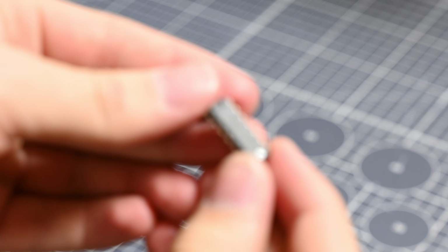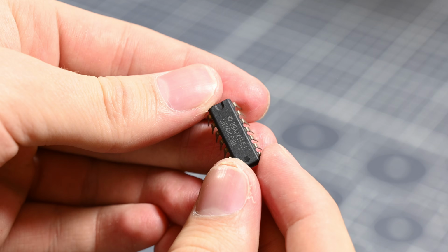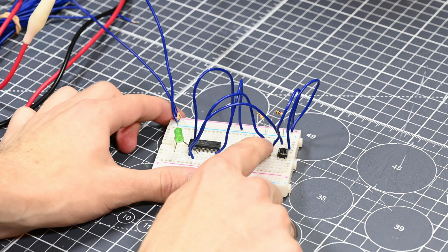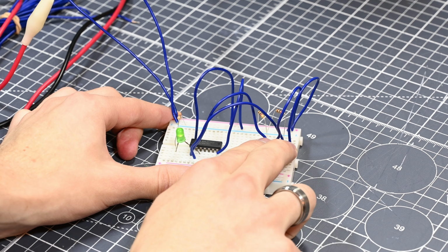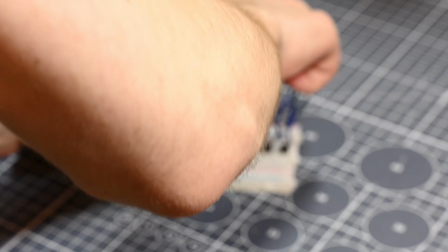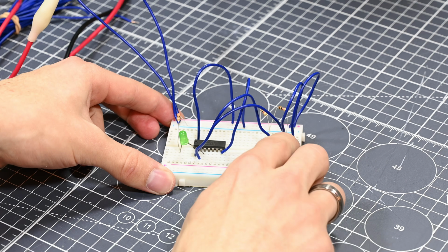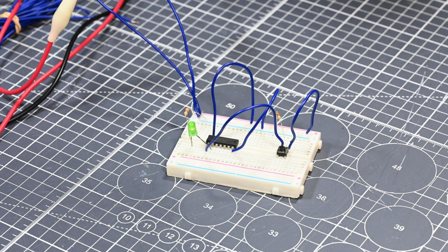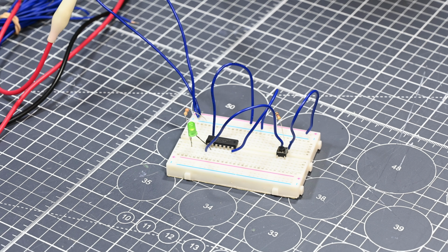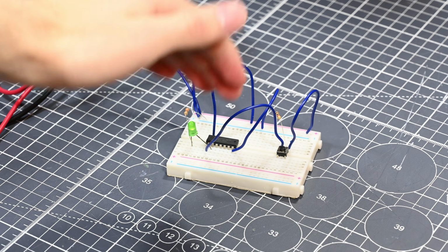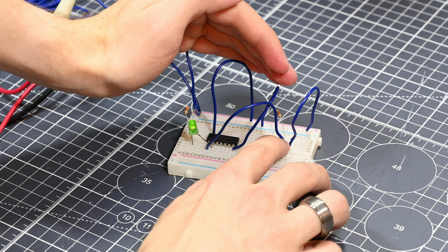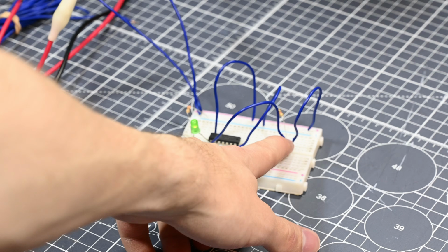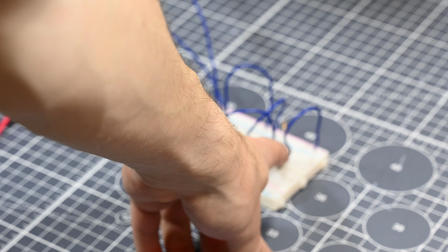For example, here's an SN74HC08N, which as you can see is an AND gate IC. This chip has 4 separate AND gate circuits in it, which can be super useful for programming logic or making a simple computer. I can switch this chip out for the SN74HC32N, which is an OR gate IC, and it behaves exactly as expected. Finally, I have the SN74HC04N, which as you might have guessed by this point, is a NOT gate IC, and it reverses the state of its input on its output. Plus, this chip has 6 separate inverter circuits in it as opposed to the 4 on the other chips, because each one only has 1 input and 1 output pin.